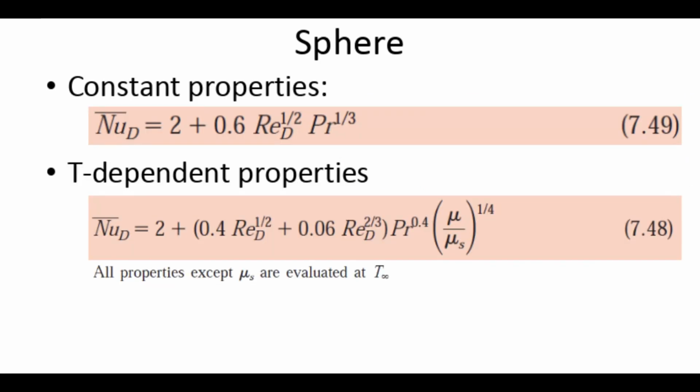For a sphere, you have similar regressions. And until we hit the time, I'm going to show you just regression on top of regression, and the story is plug and chug. Don't really care about that because I'm assuming that you can do that in your sleep. What I care is that you know what you do. Reynolds to 1/2, Prandtl to 1/3. Big surprise. I don't know if the book didn't say it or I didn't put it, but you know that is for Prandtl number bigger than 0.7. The 1/3 is the giveaway that they did it for air and water. The Reynolds to the 1/2 is much the same as we had in the flat plate. These themes keep repeating.